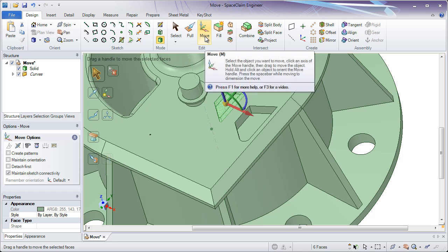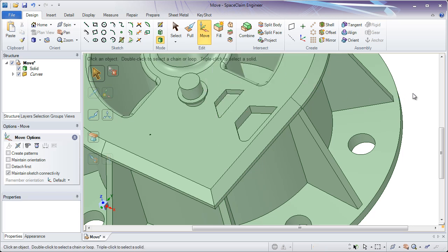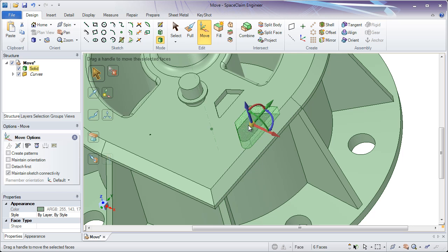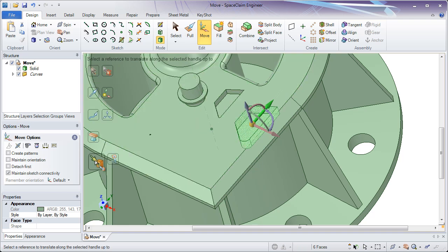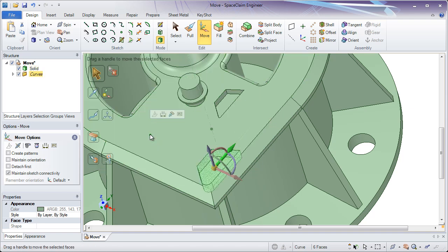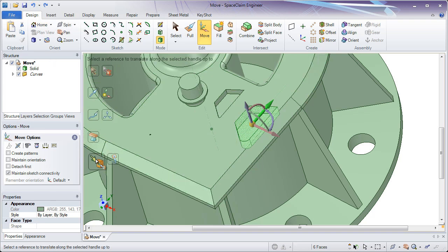For the last thing we'll do, let's look at combining two of the operations we've seen earlier. That's going to be up to and copying with Control. So what I want to do is box select that original depression, and we're going to copy it to a new location. If I click a direction, like this green direction, and hit up to, remember it moves it up to that spot. If I undo and hold the Control key before I click this spot, it's going to copy it up to that exact location.